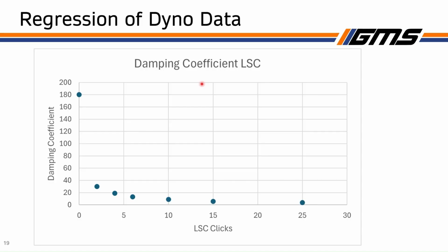And if you plot this, you'll get a graph that looks kind of like this, where the x-axis is the number of clicks, the y-axis is the damping coefficient. And you can see that you get some type of graph that looks kind of inverse exponential, like some type of decay situation, right? Where it starts out very steep and then it flattens out. And so ideally, we'd be able to just interpolate the slope for the first one, but you can't, because it's very exponential-decay-like. I'm not saying it is exponential, it might not be, but it looks very inverse exponential.